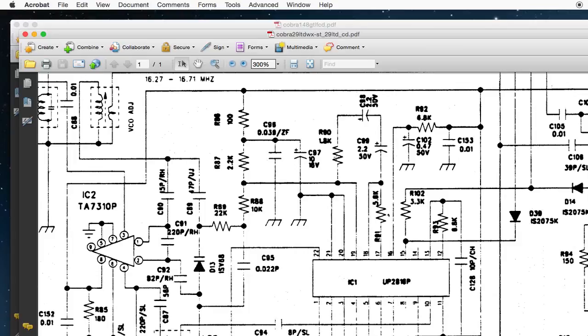So if you do get weird things like that, you might want to check these capacitors because they can go wrong. Anyway, so it comes out, and this is laid out slightly differently. This is a pull up, and there's the filters, like filter capacitors right there through that resistor.